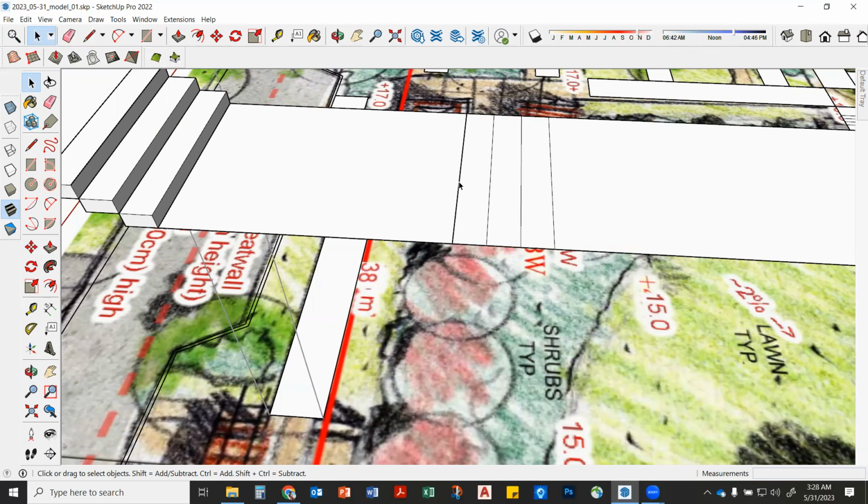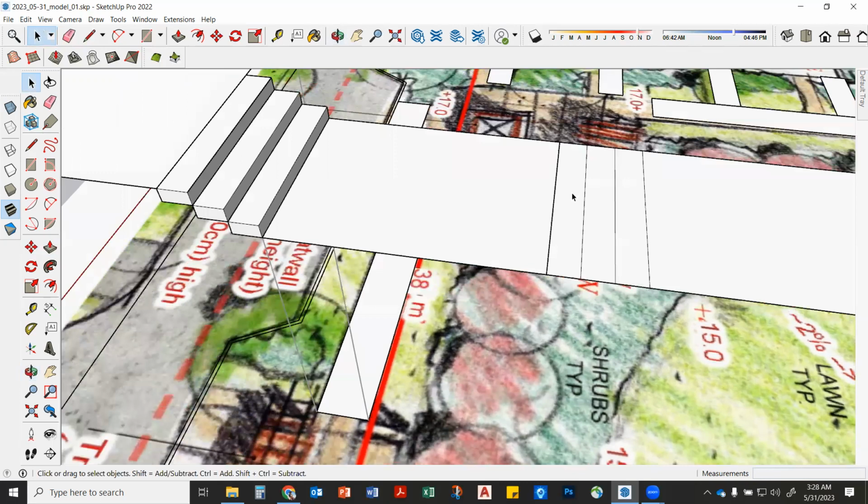Good. All we'll have to do is make this thing have a thickness, okay? But a lot of times on my construction plans, I indicate how many risers, yeah? Because if you're looking at a plan, you're like, okay, well, where does the step start? So I say 4 risers at whatever drop, okay? That's what I'm conveying. I know how many I put there, and then the contractor knows how many I put there, right? We're doing a lot of stuff, but it's good.